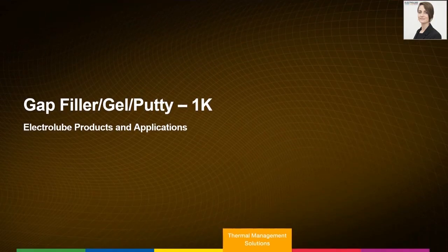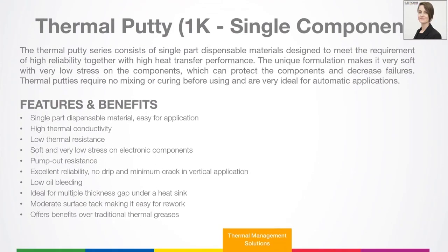There are also one-component gap fillers, otherwise known as gels or putties. It depends on the exact material type. These are single component and they're considered, let's say, pre-cured. So you can dispense them. There's no further chemical reaction that's happening, but they stay in place. They offer very low pump out resistance, again, very low stress on electronic components, and they're good for high thicknesses, vertical applications, and ensuring easy rework as well.